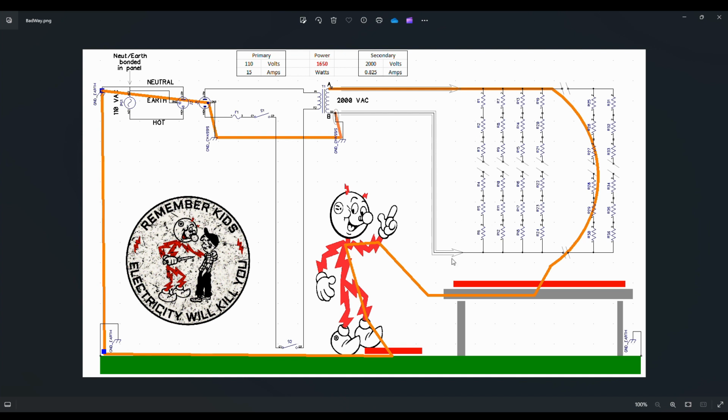So that's something we'll come back to, and I apologize for getting off this topic here. Let's just say this connection's gone bad, or this cable has gone bad, or you've had some kind of a bad return path here, whereas now the current coming up here out of terminal A down through the wood can find a path that looks as attractive to it as this one used to before it went bad.